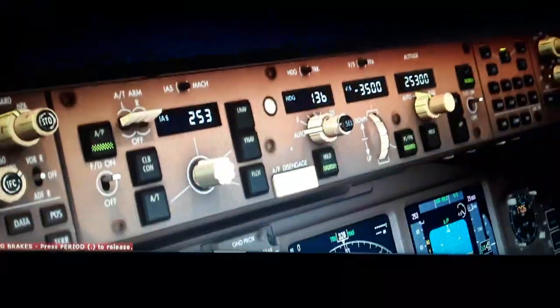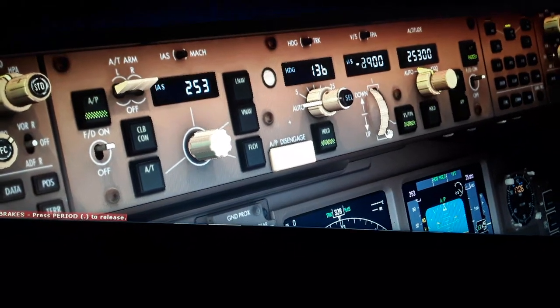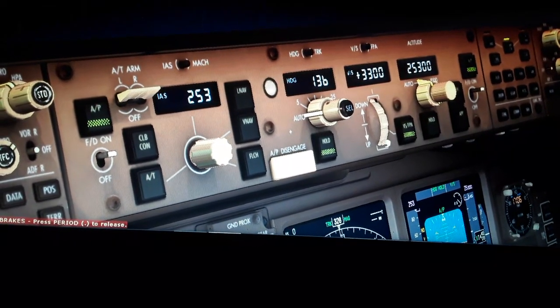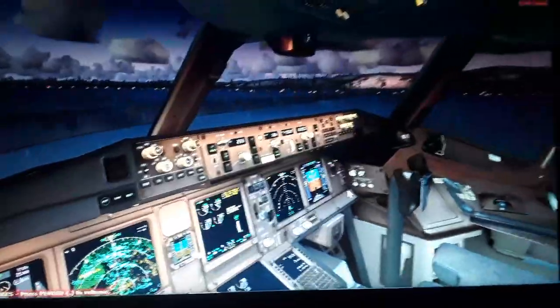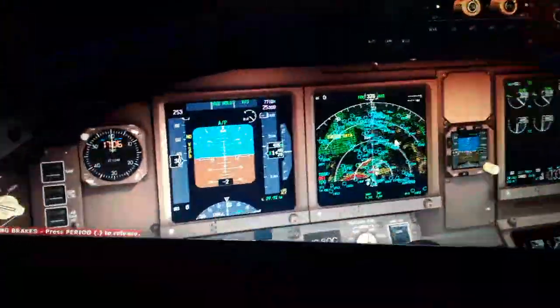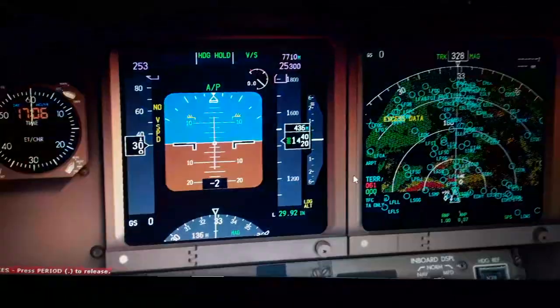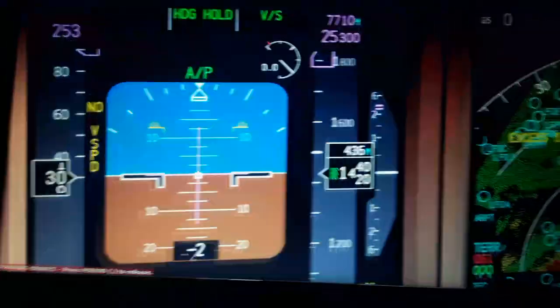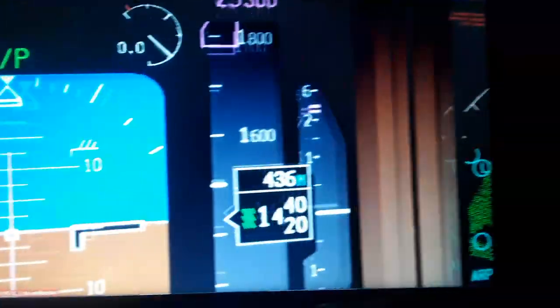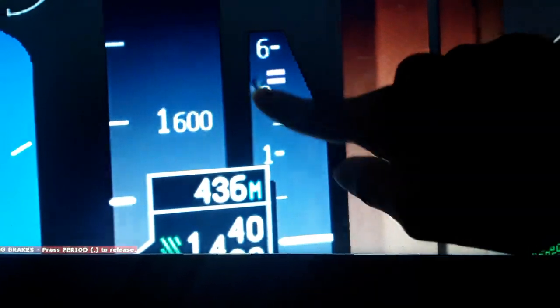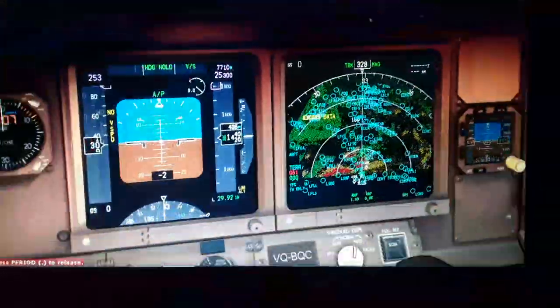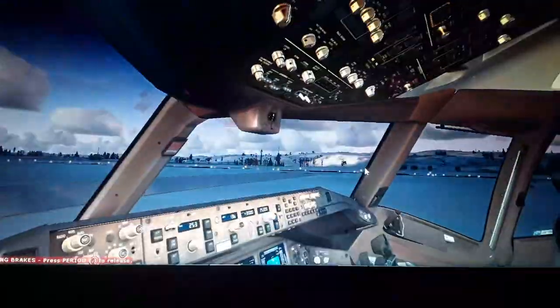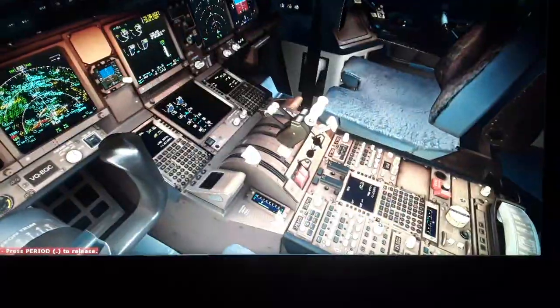So we're gonna make it the opposite way now. We're gonna have a climb like plus 3,500 feet like this. So this is gonna signal a climb rate now with the vertical speed here and the heading hold. So we're gonna have to climb to this target altitude with this target airspeed, and this is gonna be the vertical rate of climb over here, this purple line. So you have to know these things about every detail about your aircraft, how you use it.